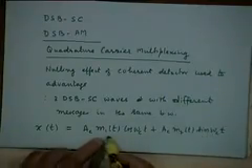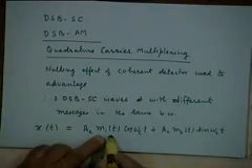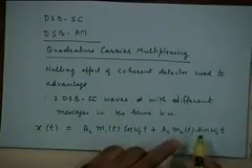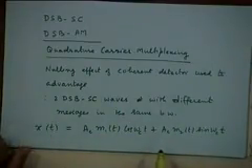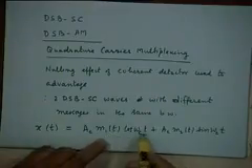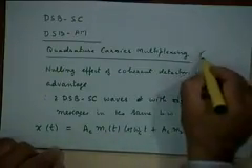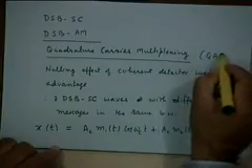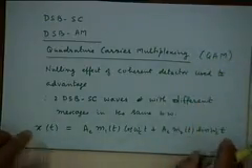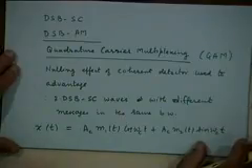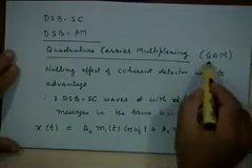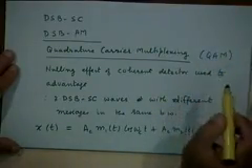Then I can reconstruct m1(t) separately, independent of m2(t), and vice versa, right? So basically I have multiplexed two message waveforms onto the same carrier. This we call quadrature carrier multiplexing. It's also called quadrature amplitude modulation, QAM.